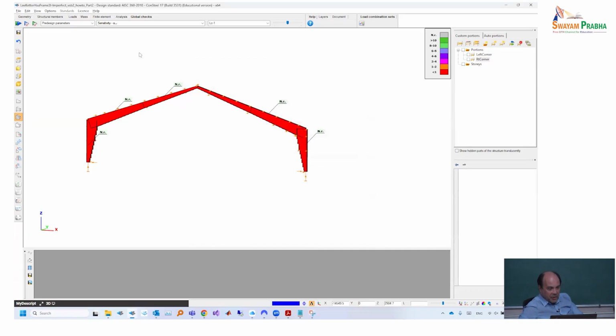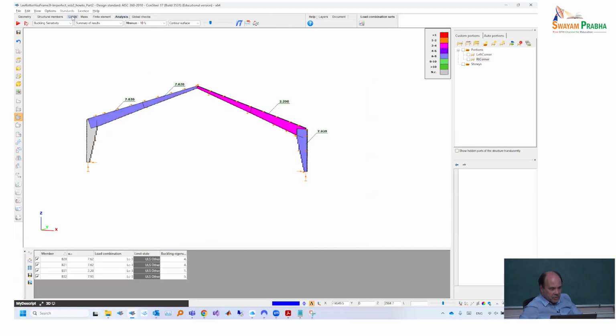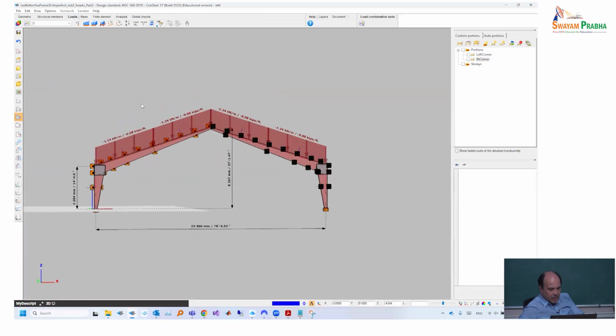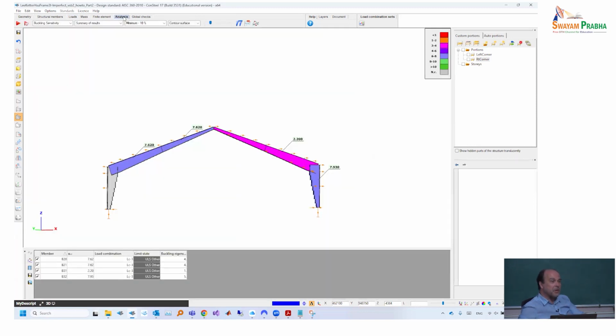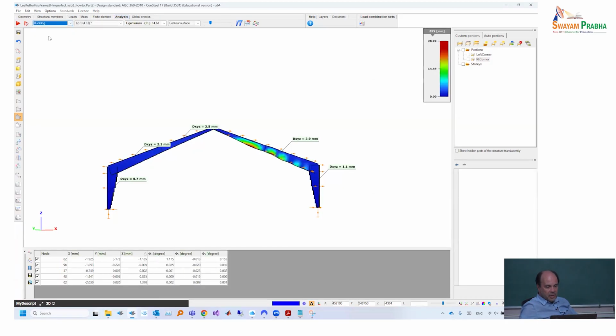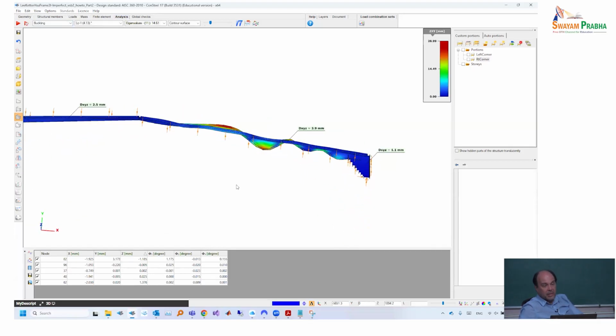There is another thing, if we already started to speak about the corner, because we were already there, that, as I said at the beginning, unfortunately, we have no B moments, we have nothing, because we haven't applied loads out of plane. But if you look to these buckling modes, then you can already see that, even if I haven't applied any load in the out-of-plane direction, the buckling modes are always appearing in the direction where the structure is the weakest, which is almost always out of plane or torsional type. So if you look to these buckling modes, then we can recognize that there are heavy torsional displacements and everything like that here in the structure.